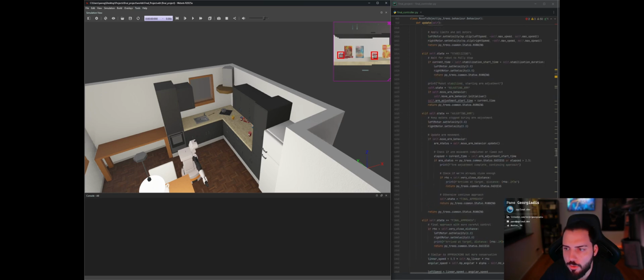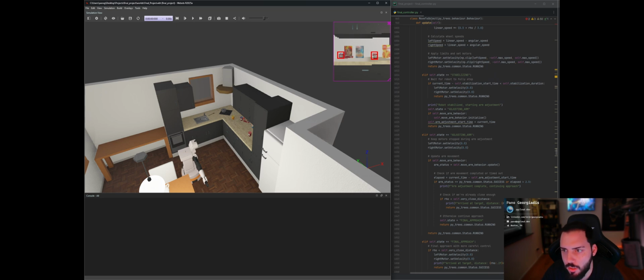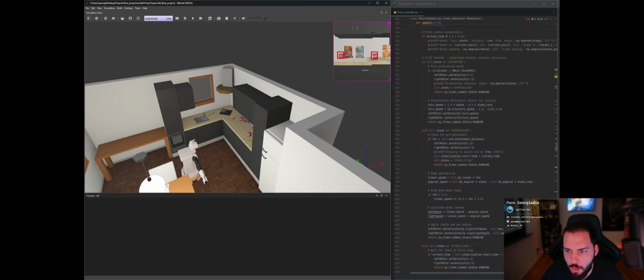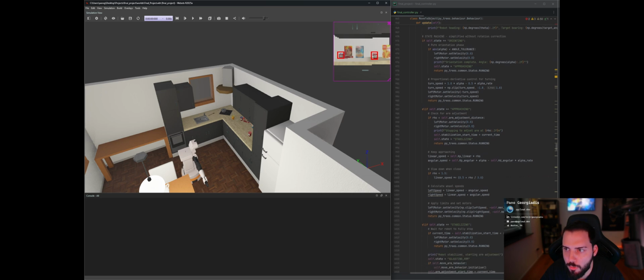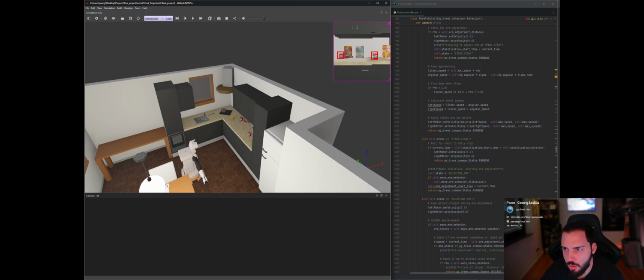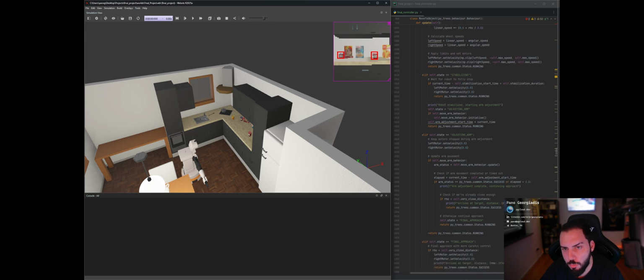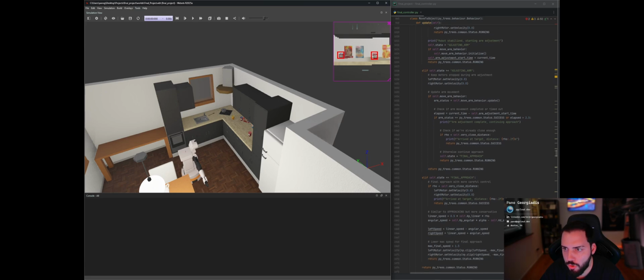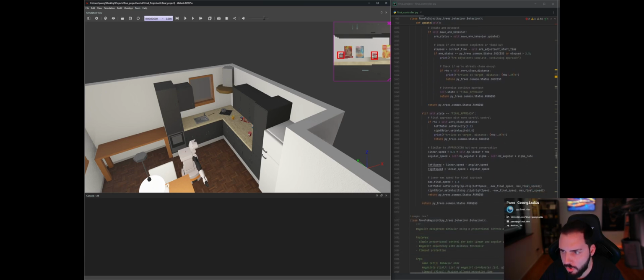And you can see the state machine has orienting, which is the rotational alignment toward the target. Then it has approaching, the main movement phase with distance-based speed control. Then it has stabilizing, for motion dampening to ensure precise positioning. Adjusting arm is the coordination of the arm movement during the final approach, and then the final approach is precision positioning with slow controlled movement.